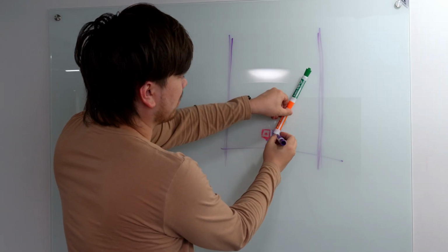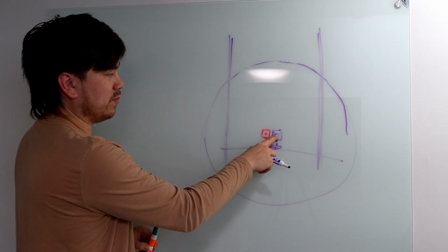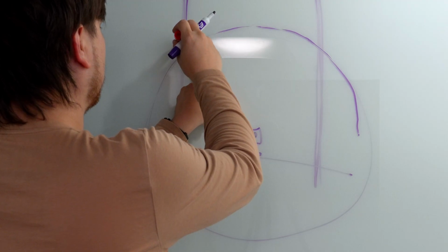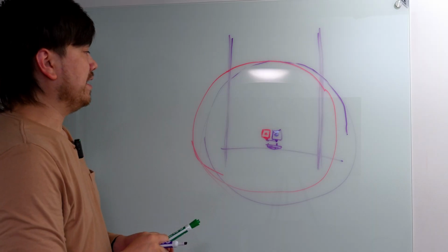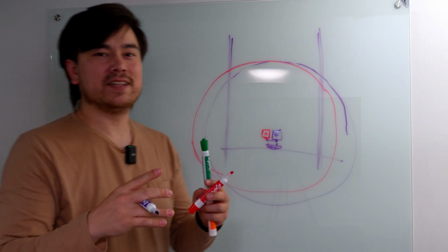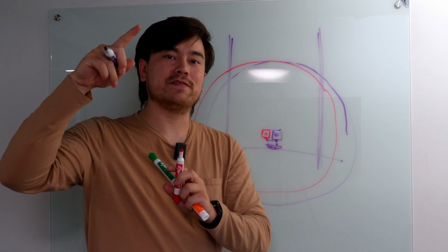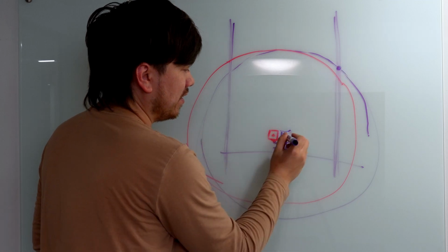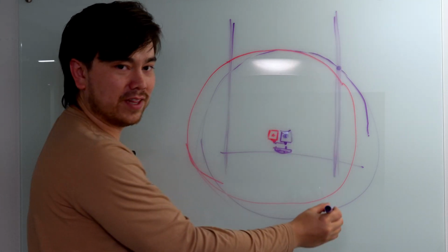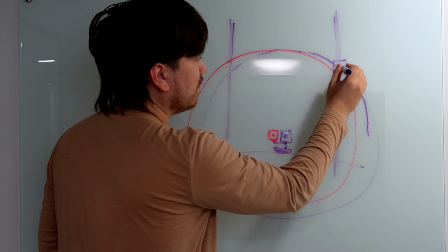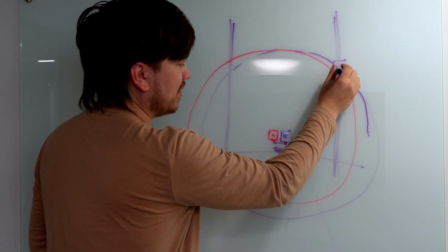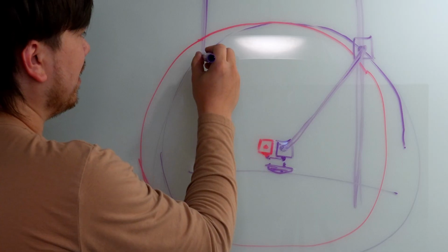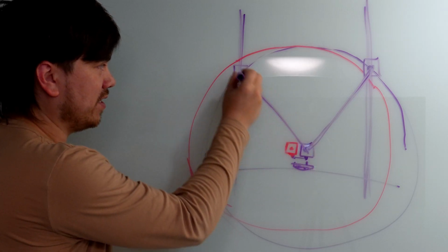We're going to draw a circle around this point. There's our circle for the first state of that print head, and we'll draw another circle for the red. We're just going to draw another circle just like this. Okay, so we have our two circles, and basically those circles are the same length as the carbon fiber rods that are inside of the printer. What we do here is we just find the intersection point of the circle with the linear rail. And that's where we want to move our block to. We want to move that block right here, and then we can draw in that carbon fiber rod. And likewise over here, draw in our carbon fiber rod.